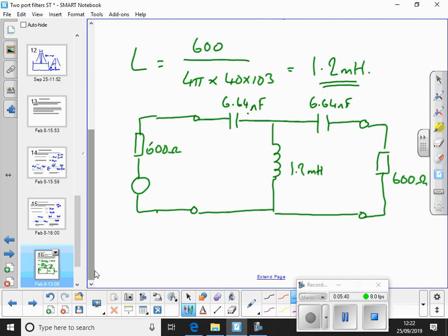The idea is that filter design software is a useful aid to designing a filter and finding out what you might get when you build it. Because you could put component values at all the lowest tolerances and all the highest tolerances in LC, and find out how the component tolerances could affect your design. Okay. The thing is, in some cases you might get two inductors where this one's 10% above and that one's 10% below, and that kind of partly cancels each other out.